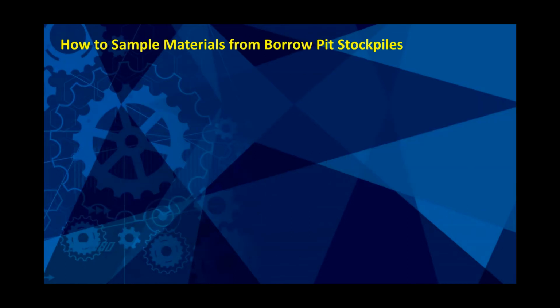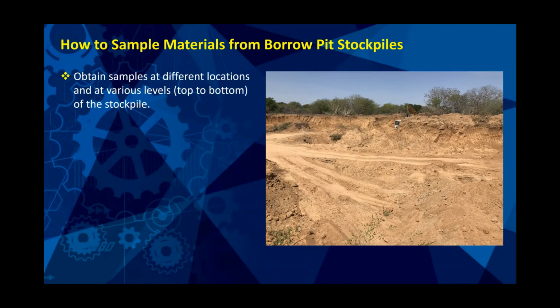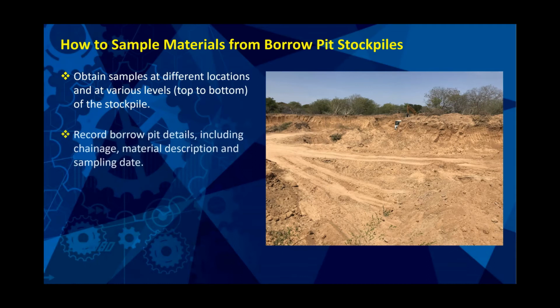How to sample materials from borrow pit stockpiles. You have to obtain samples at different locations and at various levels of the stockpile. Record the borrow pit details, including the chainage, material description and sampling date.